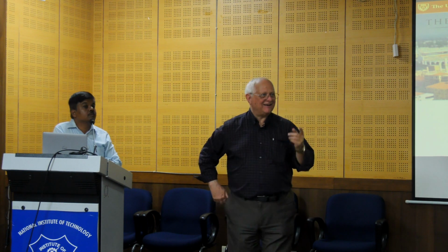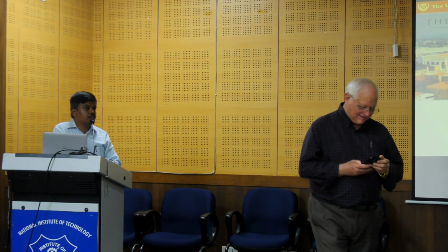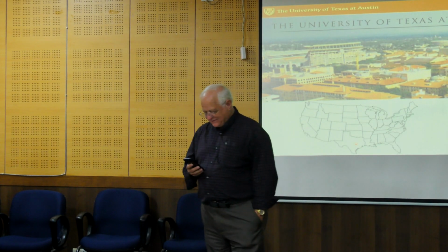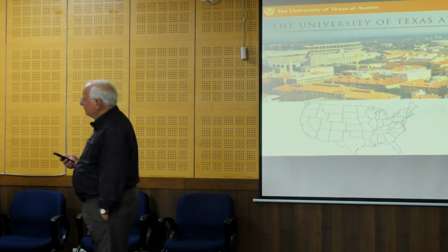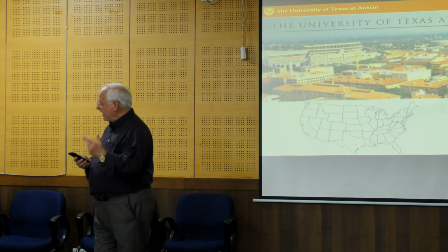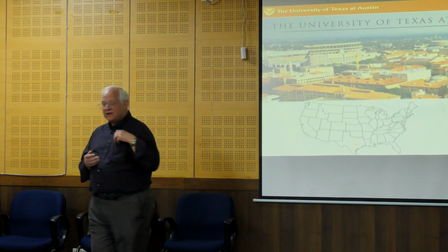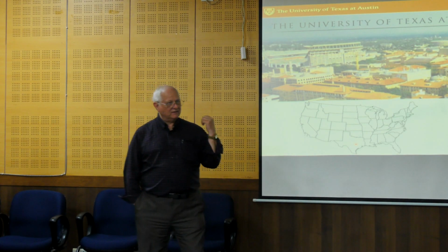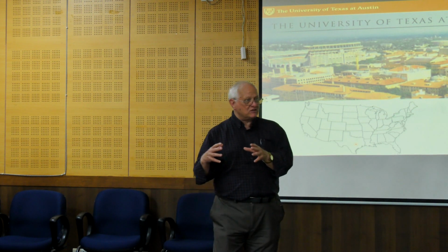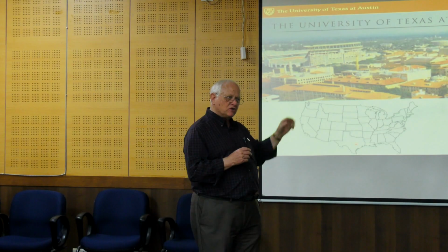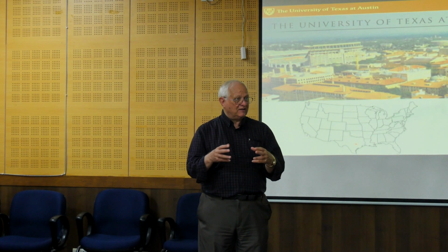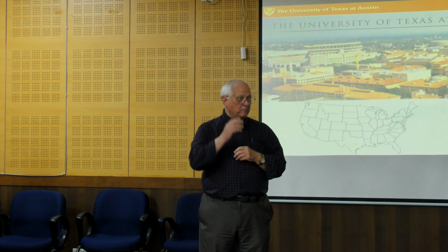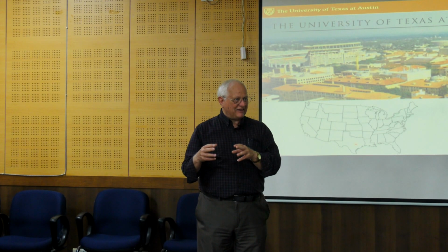Yes. Sure. Can laser direct energy deposition be applied for manufacturing cutting tools? Let's see what I have here. It's asking whether laser energy deposition can be applied for manufacturing some kind of cutting tools. Oh, use additive to create cutting tools. Yes, it's a good question. Tooling certainly fits the application space. We talked about tooling. The tools I showed were primarily forming tools, but cutting tools reasonably could be made if we can get the right feedstock, right?